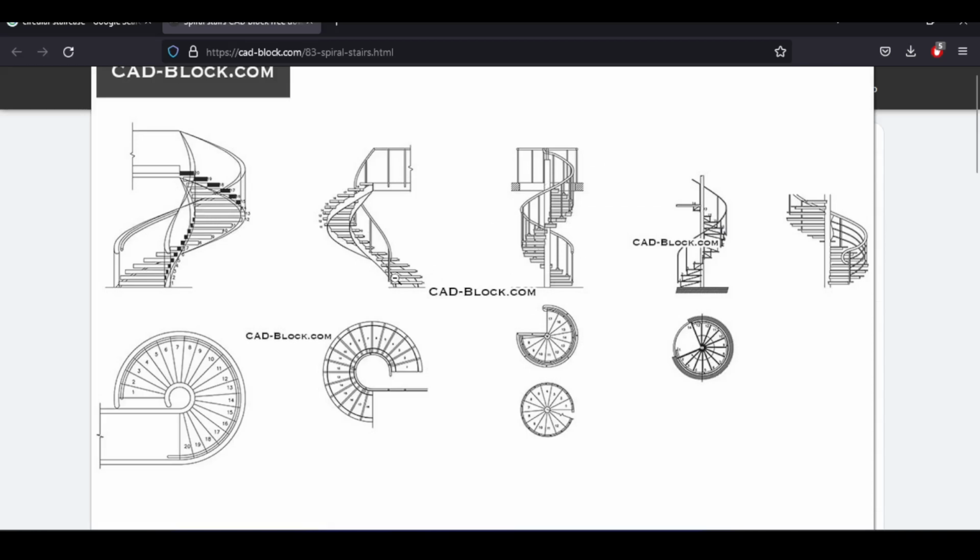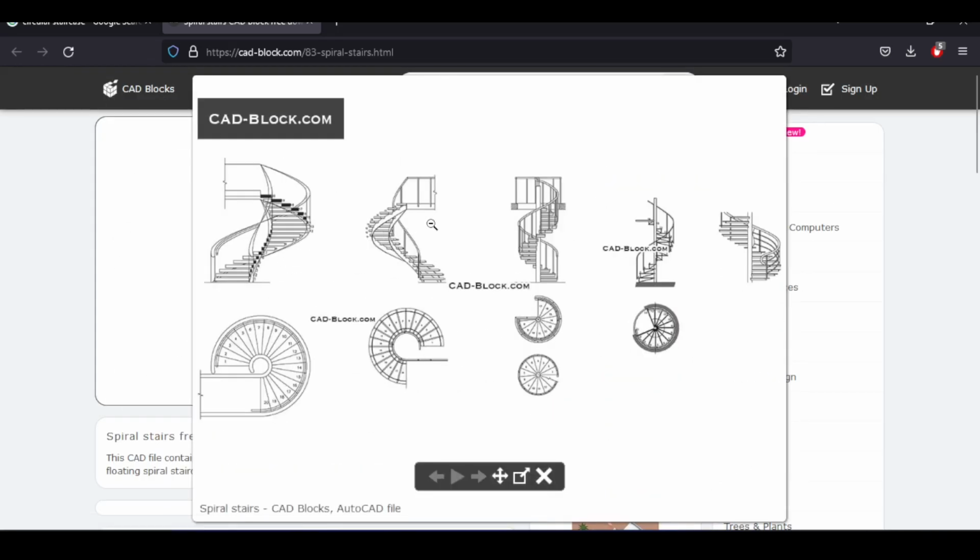Then I will talk about this staircase, which is going to be two staircases. The first is a concrete staircase. In that case, you would have a slab or a shell that is basically rotated in a helical way. The second staircase is this steel staircase. In that case, you would have two helical beams curving up besides the little steps you have here. I would basically use something like this: a smaller step on the inside, a bigger step on the outside. Of course, feel free to use whatever you want. I'm going to use this, basically.